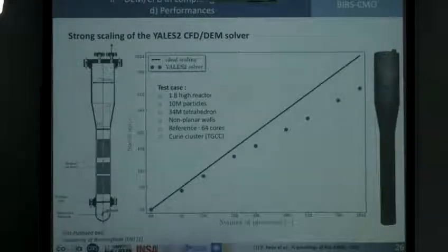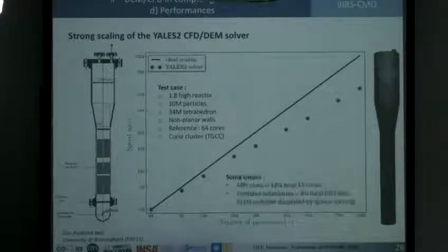It's the strong scaling of the code on the gas fluidized bed, which is experimented in the University of Birmingham. We will talk about this a bit more later. It's filled with 10 million particles and 30 million tetrahedra, and of course, because of the cylindrical part, it's meshed with tetrahedra. Here again, the results are quite satisfactory. Looking at some timers, we could notice that the MPI communications in all of these cases represented less than 12% of the total CPU cost, and the complex boundaries management represented less than 4% of the total CPU cost. That was a good validation for our numerical methodology.